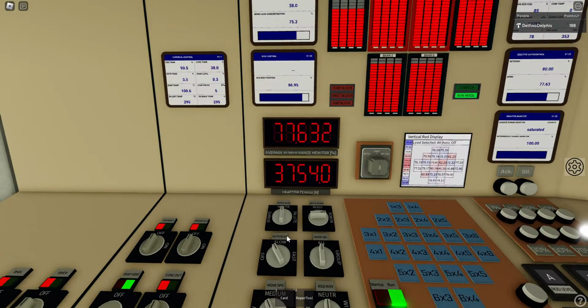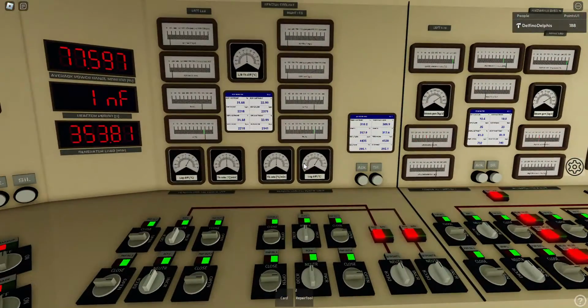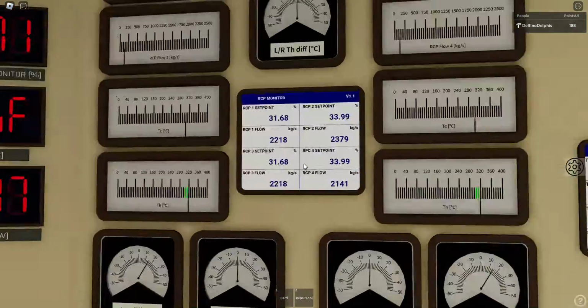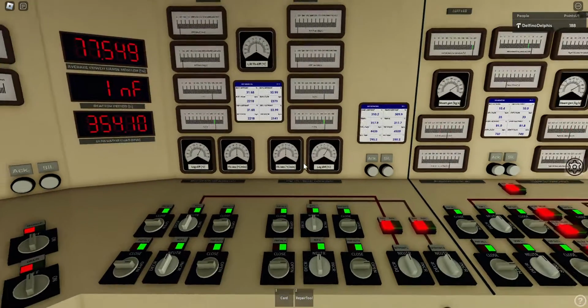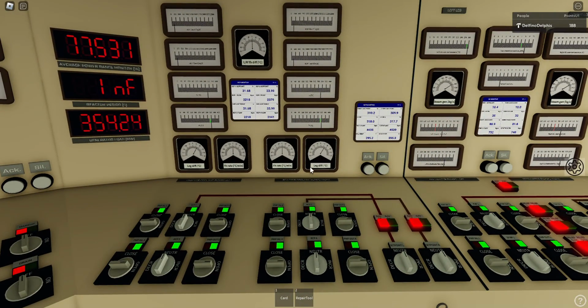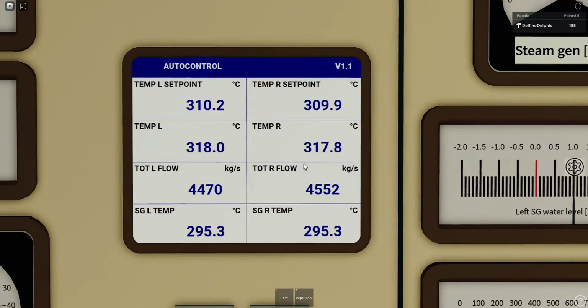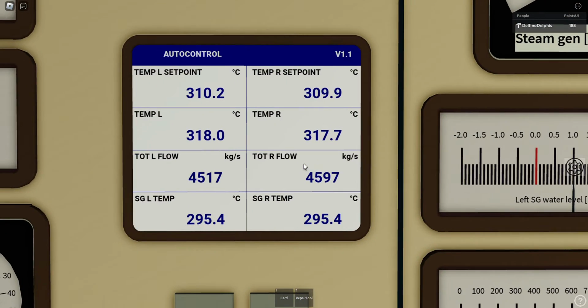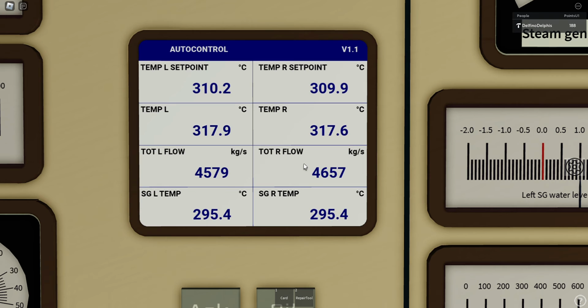It just won't work. Why? Okay, let me just stop this reactor here. You see it stopped, it's even dropping a little bit. And let's say I will increase the coolant flow, it's pretty small at this moment, to reduce this temperature. Look what happens. So the temperature is now dropping, obviously.